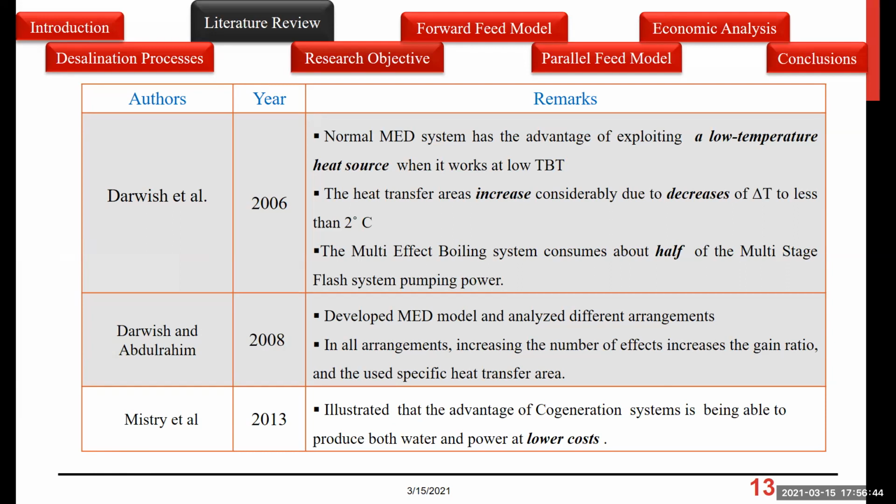The heat transfer rate depends on the temperature difference across the effects. And he said again, in comparison between the MED and the MSF, MED is basically consuming about half of the energy needed for the MSF. Then Darwish and Abdul Rahim developed an MED model and analyzed different arrangements: parallel, forward, backward, and so on. For each one of them, they found that the number of effects is the most powerful parameter that controls the value of the performance ratio.